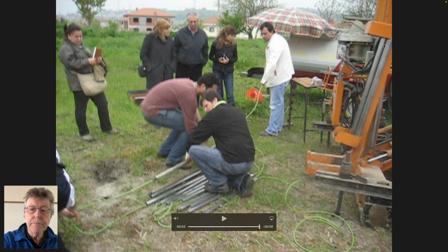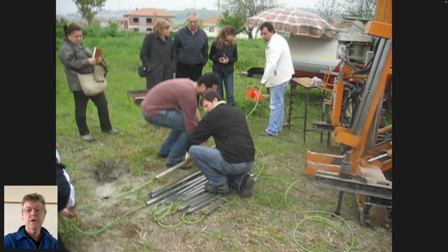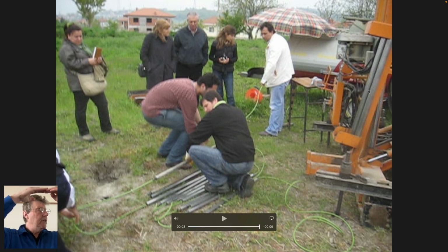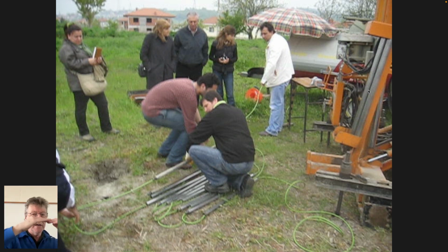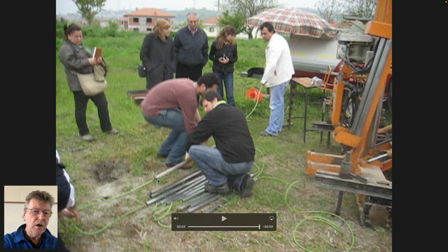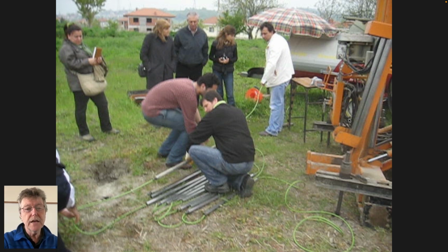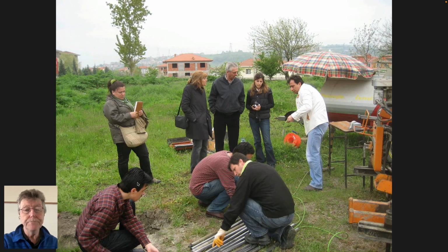So this is a geoprobe tester. It's a vertical arranged guide with a mandrel on a turntable on top of it. It doesn't turn, but it pushes down. It takes these roughly 1-inch diameter pieces, look like they're about a meter long, through which you thread cable to the tip of the cone, and then you assemble them here and then be able to run them at constant penetration velocity of 2 centimeters a second, and you record the end bearing pressure, the sleeve friction, and the pore pressure of the tip, and record it digitally through this cable.